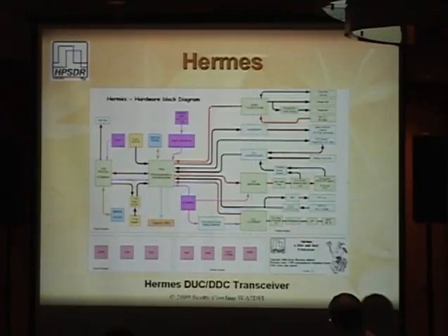This is the block diagram. Again, a nice eye chart here. And the thing that they put on here is, since we took these 3 boards and kind of mashed them together, we took a single FPGA that is the biggest FPGA we could buy that's not a BGA type. So the biggest leaded one that we could get, which is a Cyclone 3C40. And so basically all the components of Aussie, Penelope, and Mercury are all going to be mashed together into this one FPGA, so we picked the biggest one we could get.